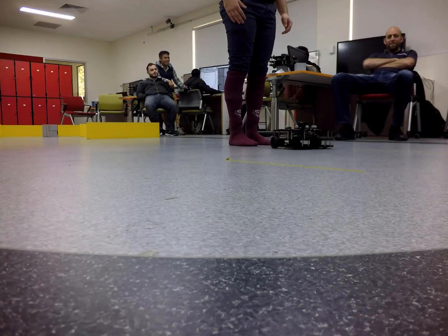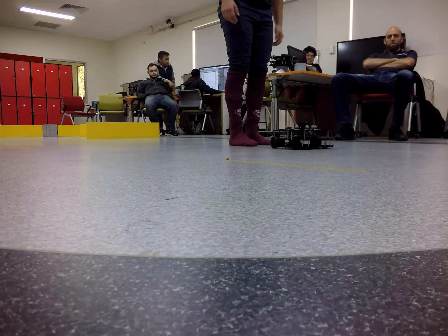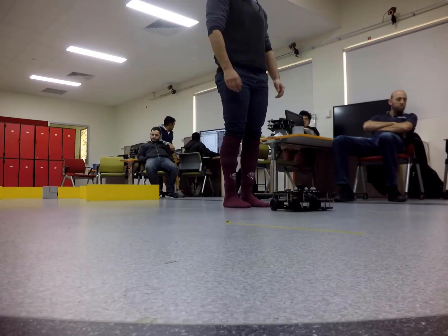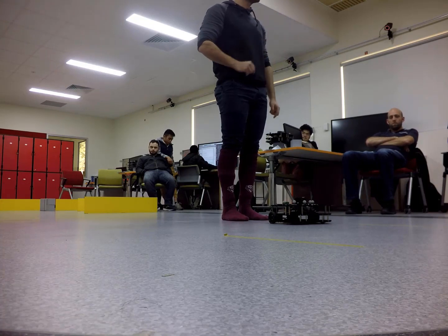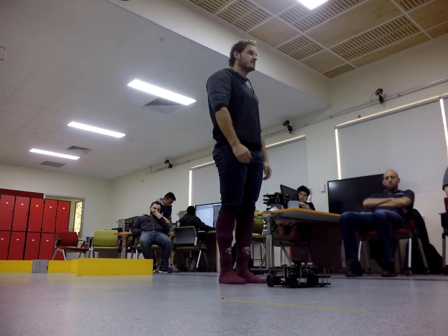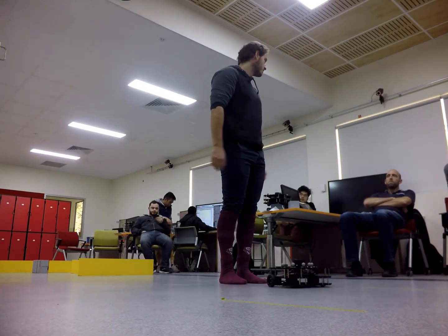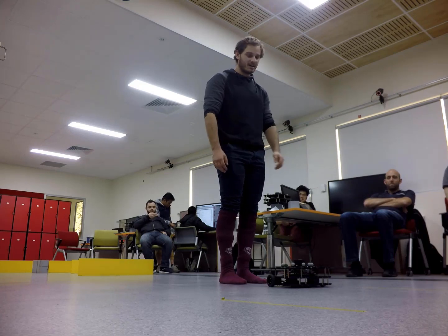What I'm doing is using a convolutional neural network to detect a human, and then I'm reconstructing the bounding box outside of that human, checking for the number of pixels that are of their own colour. If there's a certain number of those pixels, then it will follow that person. So if someone else were to jump in, it shouldn't follow you.